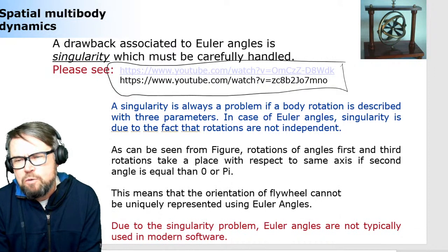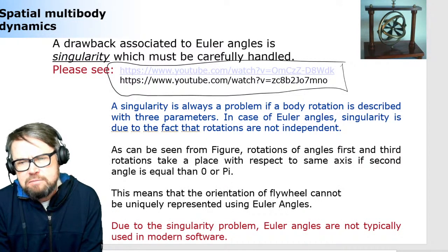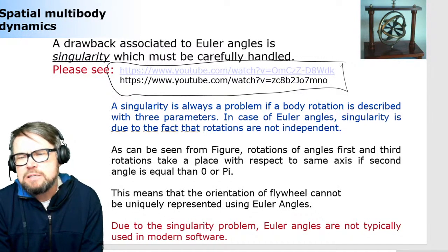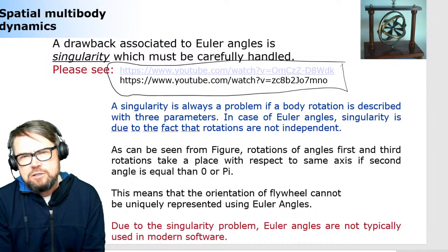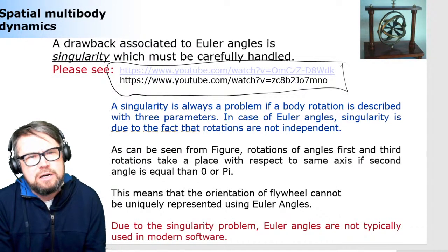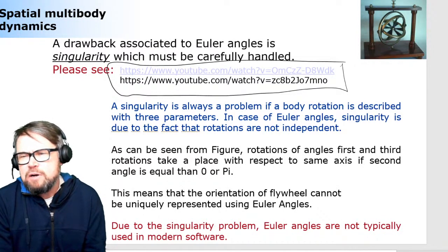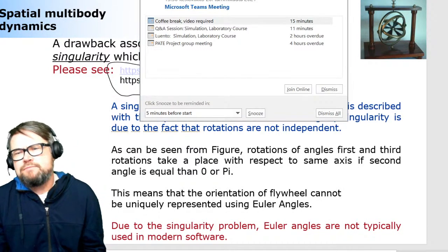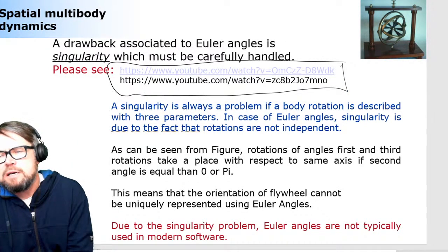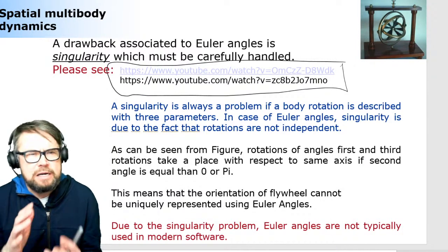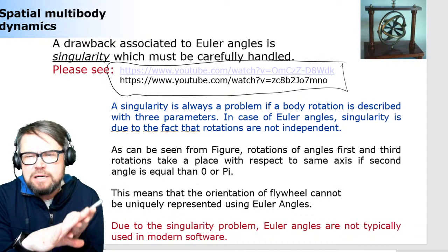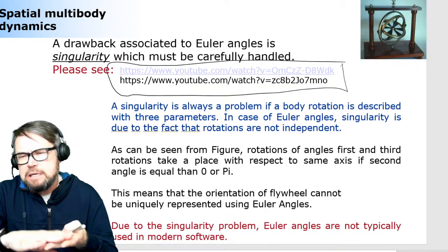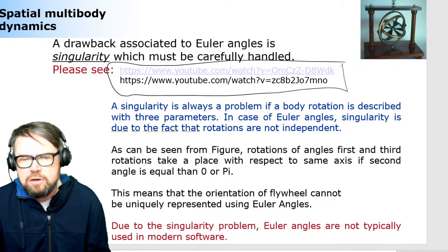Numerically, there are many different ways to avoid gimbal locking. You can add some artificial rotation to your system. You can deal with that in many different ways. You can monitor the rank of your rotation matrix and recognize when you start to face some difficulties. But when you have an apparatus that is measuring angles, like a gyro, this can go to a configuration where these 2 axes are parallel, making it not possible to see the full orientation of the system. So that's what is called gimbal locking.